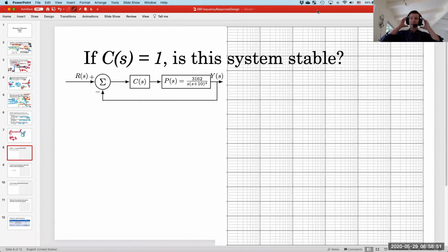Yeah. So if you additionally introduce a low-pass filter, like we did in lab, then if you put them all in cascade, you are filtering all of the branches, the P, the I, and the D. Where if you do them in parallel, you can put the filter only on the derivative term, which means that you get the most bang for your buck out of the proportional and the integrative term.